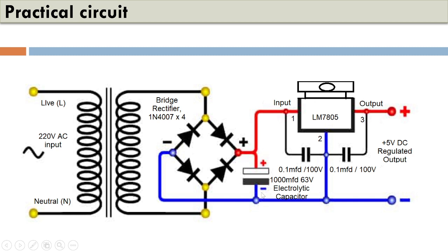If the output voltage is say 12 or 18 or within 20 volts, then it is very safe to use a capacitor rated 35 volts or more. A voltage rating almost equal to the expected voltage is not recommended. It is always recommended to have a capacitor voltage larger than the expected voltage across the capacitor.